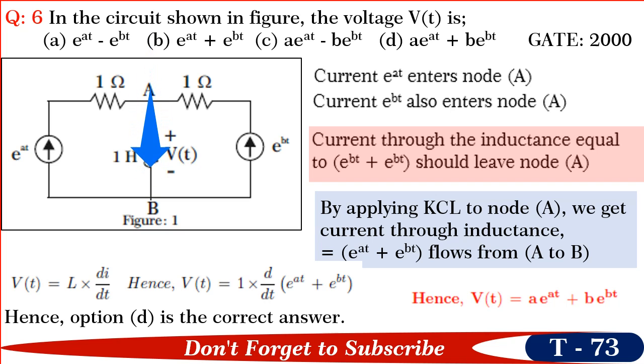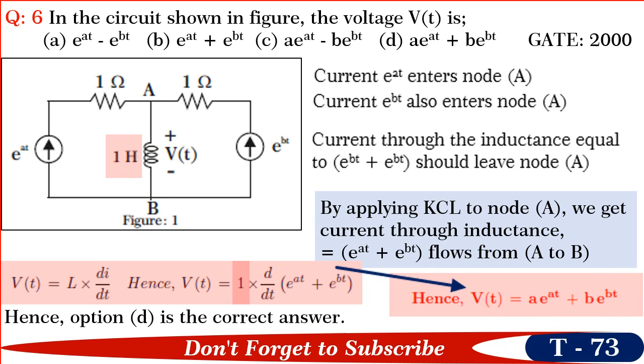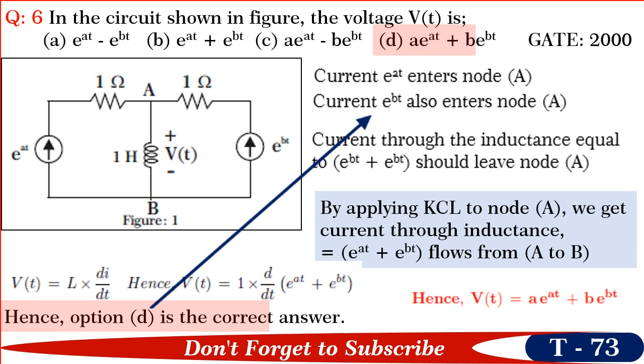But we know voltage across the inductance V of t is equal to L into di by dt. Hence, V of t is equal to L into d by dt of e to the power of at plus e to the power of bt. By substituting L is equal to 1 Henry and solving, we get V of t is equal to a into e to the power of at plus b into e to the power of bt. Hence, option D is the correct answer. Very simple and easy, isn't it, friends?